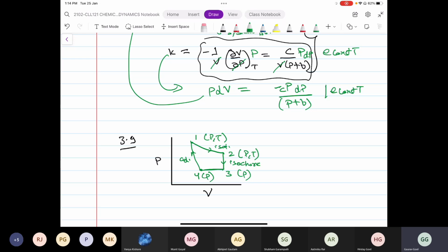Then they're asking you to do some calculations about internal energy change, heat, work, etc. I'm not going to do those calculations, but it's clear that calculations can be done if the state point is fully specified. So that is the key task here. If my state points are fully specified, I can complete the calculation. Here you can see it's a pure species. I need to specify 2 variables at points 3 and 4. That information is lacking right now.